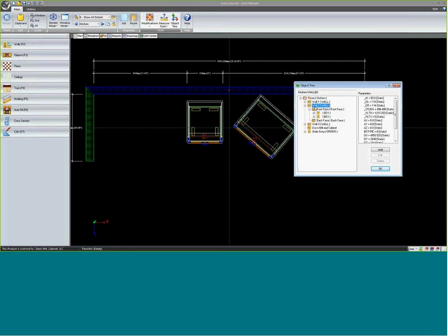Let's pick up here first on the room, and we'll look at just this cabinet. If I click on this cabinet, and remember we're on the BD1, so I think it's this one right here, but this one's a 534 millimeter wide one, so we'll find out. I'm going to scroll down the parameters and find the DX parameter. Wrong, it's this cabinet we're looking at. So 762 millimeters wide is this cabinet. I could look up here. There's one parameter we didn't talk about, cabinet number, cabno. It's number 2 on this one. The sequence you show up in the object tree is somewhat arbitrary, so you never quite know which one you're looking at, so you need to confirm that. But this one then is this rotated cabinet.